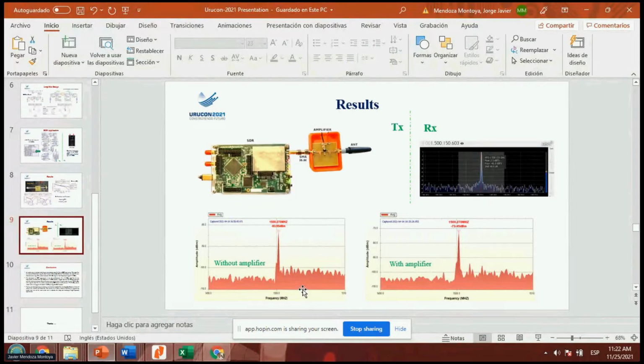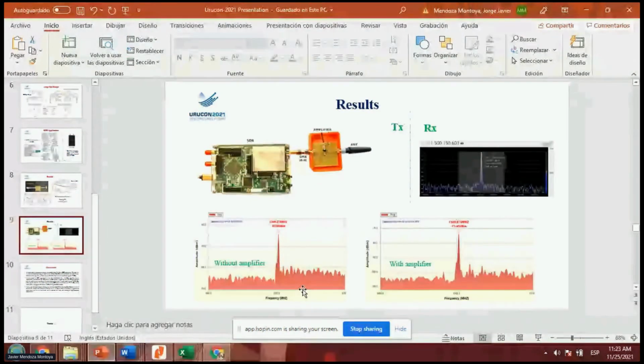There is a little bit of difference here because using the VNA characterization of this amplifier, we got 12.4 dB of gain. But what happened here, most probably, is that there is power loss using this connector, because it affects the real measurement.